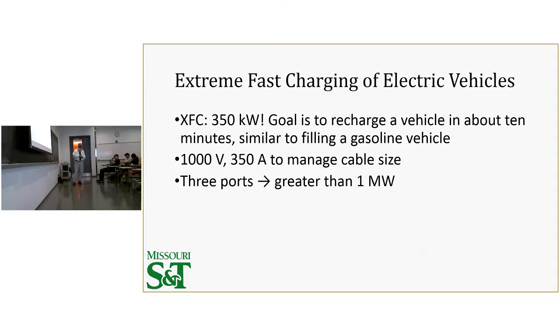The other thing is that you wouldn't have just one of these chargers. Dr. Gross was saying that Meyer has 8 Tesla supercharger stations. Well, we're just looking at 3, but 3 times 350 kilowatts is over a megawatt.